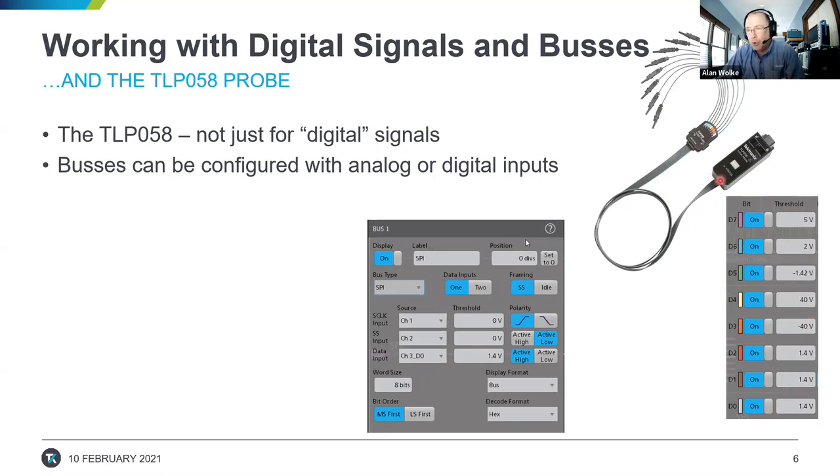So this logic probe could be used to look at not only logic signals and digital signals, but it could also be used to look at mode pins, discrete signals in an aircraft. It could be looking at power supply states or something like that. So for example, if you had a complex trigger condition you wanted to trigger on, hey, when this power supply comes up and this one goes up and then this pin cycles low, I want to trigger when that happens. Right? Rather than burning 3 scope channels just to set up your trigger, you can do that with 3 of the inputs on this logic probe. So it just extends some of the capability beyond just doing logic.